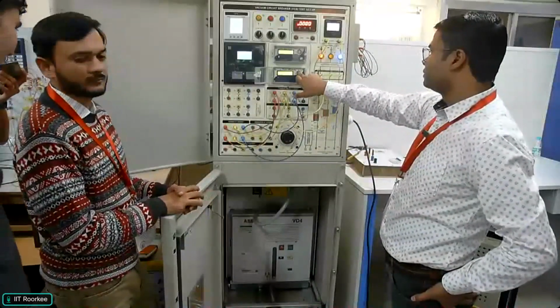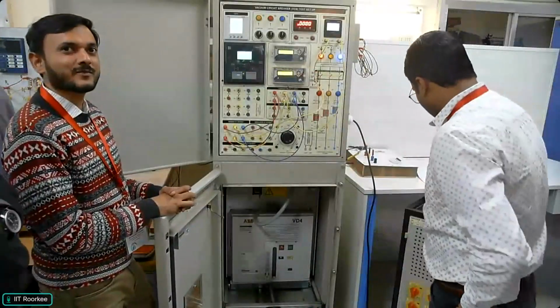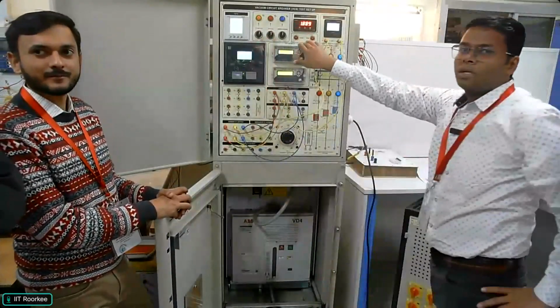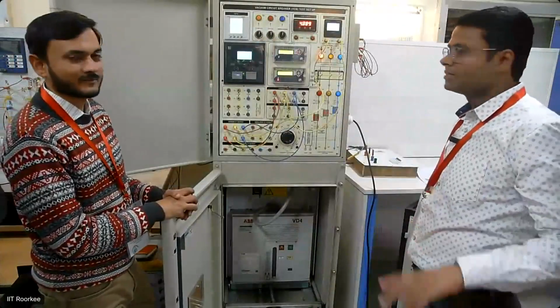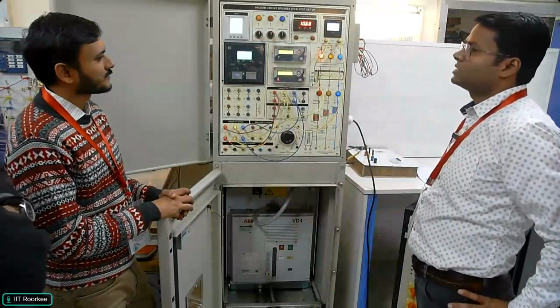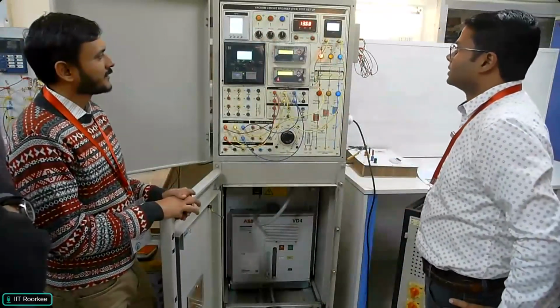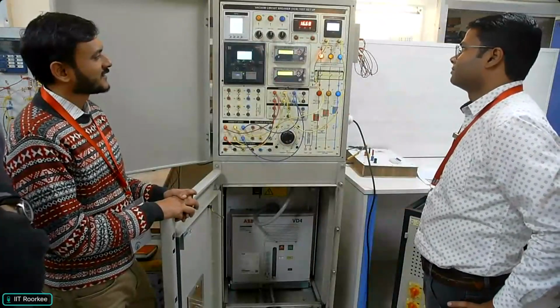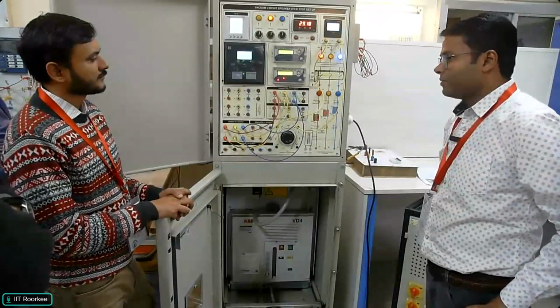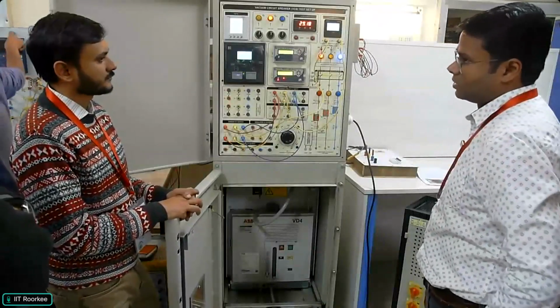The other thing we will do the same. Here again we will do it for 1 ampere. Earlier for standard inverse, it was taking nearly 17 seconds, so let's see how much time it will take. The same thing we are doing for 2 ampere. It has taken 29.19 seconds, maybe due to the low value of load fault current.